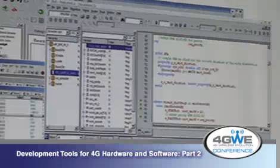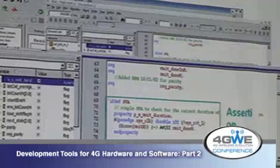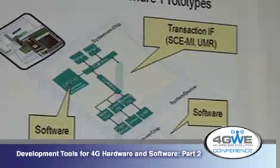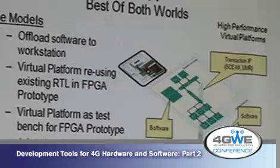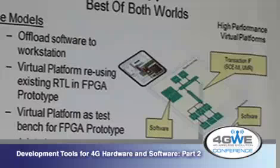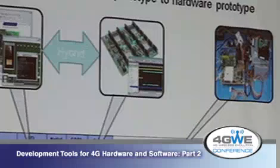So this is an example here. I have a platform with software attached to it, and I go all the way down to the Verilog, which is the language in which the hardware is developed, with things like assertions, the hardware equivalent of breakpoints, and I can co-debug all this together, even connecting the high-level world with the actual prototype, so I can take the best of both worlds here and offload my software from here to the workstation, use it as verification reference, or connect to outside interfaces like the air interface and hardware, and still keep my software simulation in that same context.